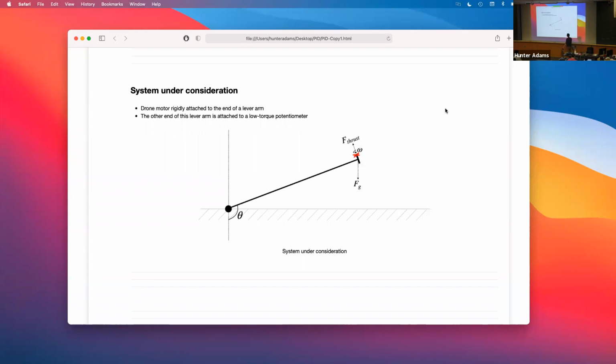But you're being asked to control it up to at least 30 degrees above. And in particular, at boot up, you're asked to have this arm swing from hanging straight down up to horizontal, plus 30, minus 30 horizontal. And then the user should be able to enter any angle.